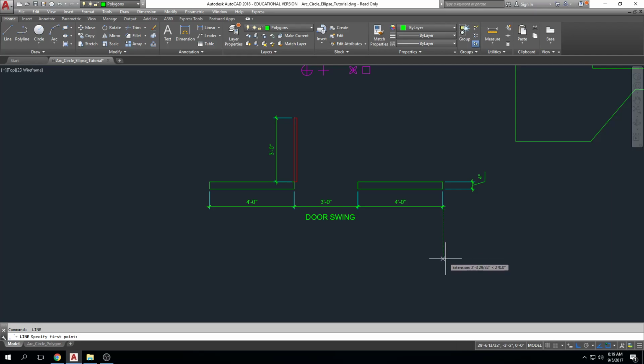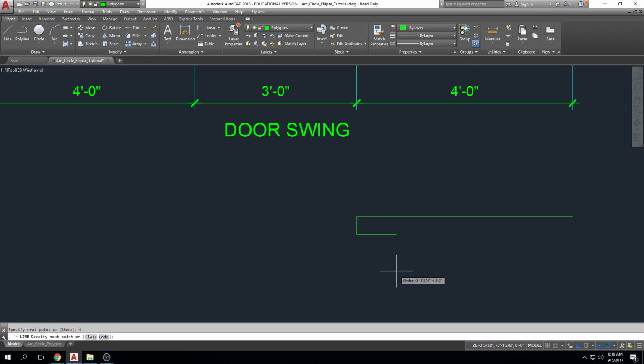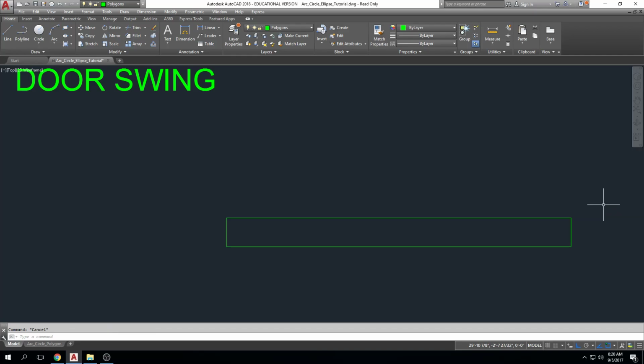I'm going to come down here to draw, for example, this wall. I click, initiate my command. I know that it's 4 feet in this direction, so I type 4 foot, enter. I know that it's 4 inches in this direction, so I move my mouse down, type 4, enter. You notice my mouse is off to the right side of that line, and you're thinking, does that make my line not straight? Well, if I have ortho on, it continues to be straight. If I didn't have ortho on, it wouldn't be, but ortho constrains it. So even though I'm over to the right when I enter that dimension, it is still drawn straight. I move in the direction I want to go, another 4 foot, enter, and then I come up here, use my endpoint snap, click and escape, and I've drawn that portion of it.